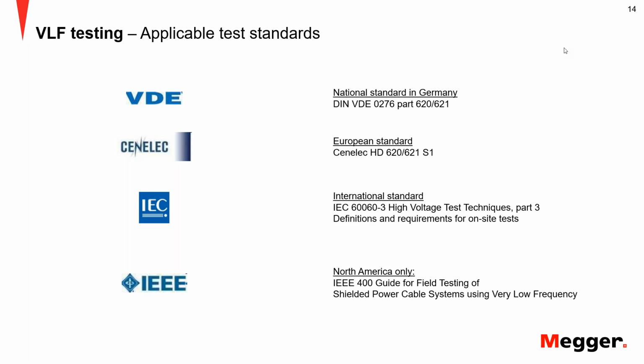The 0.5 U0 to 1.5 U0 range is related to the tan delta. The 3 U0 is the factor for the withstand test. So the withstand test is the withstand test. It has its table in IEC, it has the prescribed values. That is just your hipot. The tan delta is a defined test sequence independent of the withstand test.